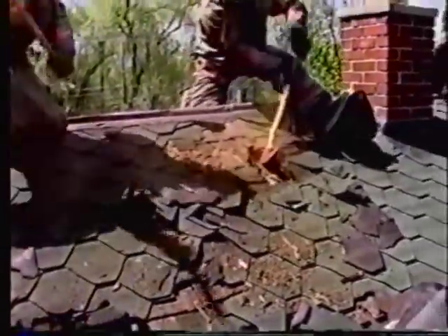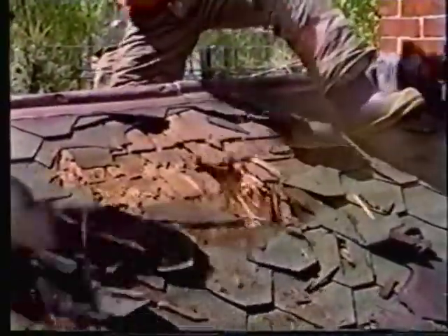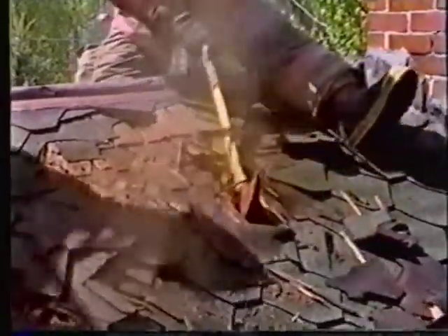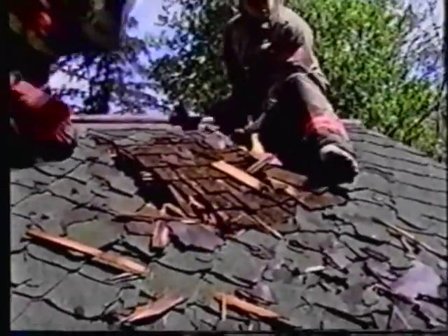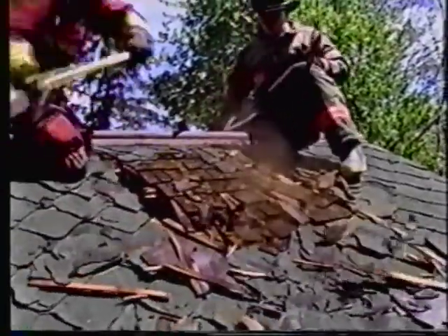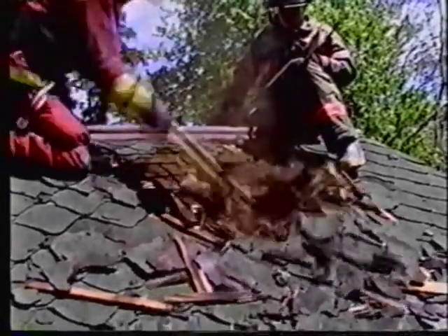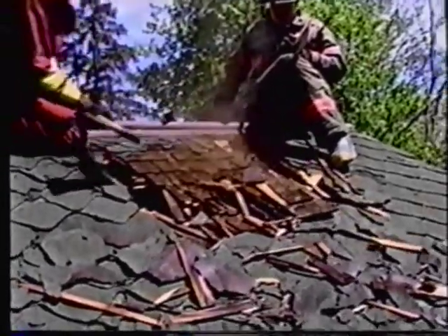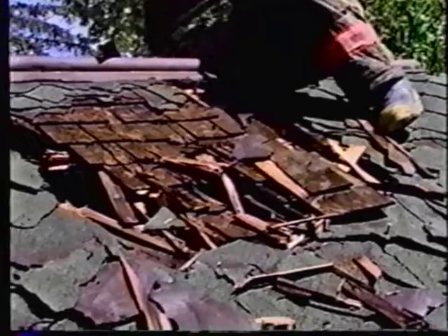The decking may be cut or broken. When cutting with the blade end of the tool, cut as close to the rafters as possible. If breaking through the roof boards, a technique commonly used for older construction with tongue and groove decking, use the back of the tool and strike between the rafters and remove the broken pieces.